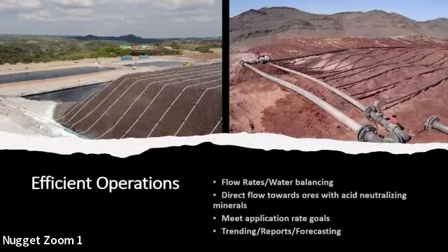The evaluation of the potential for liquefaction in terms of safety factor used the cyclic resistance ratio, which was evaluated against the cyclic shear stress ratio evaluated directly from the CPTU, gathering information from the heap leach facility.